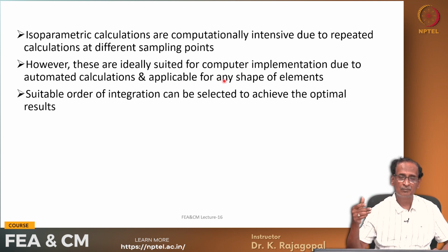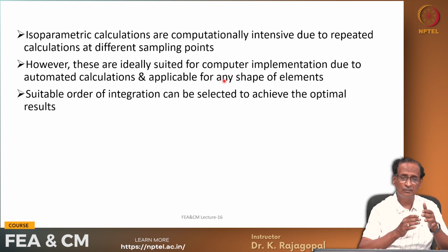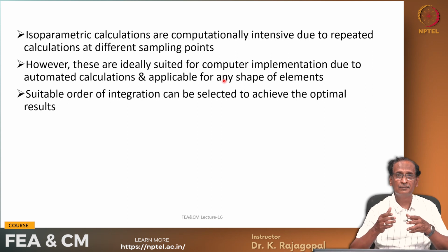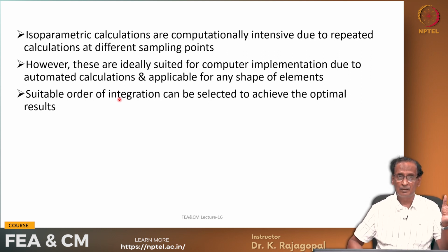Whatever the shape in the Cartesian space, we convert to some standard shape in the natural space and do the calculations, and we can choose the order of numerical integration based on the order of polynomial that we have.